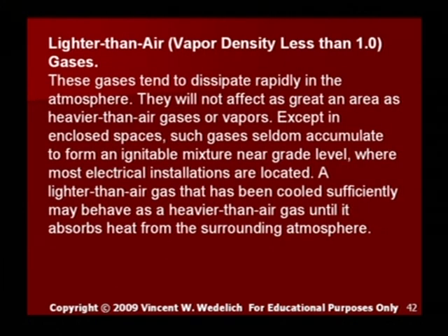Lighter than air, vapor density less than 1.0 gases. In the National Electrical Code, Article 500, you'll find a list of all the gases, and they give you the vapor density. These gases tend to dissipate rapidly in the atmosphere. They will not affect as great an area as heavier than air gases or vapors, except in enclosed spaces. Such gases seldom accumulate to form an ignitable mixture near grade level, where most electrical installations are located. A lighter than air gas that has been cooled sufficiently may behave as a heavier than air gas until it absorbs heat from the surrounding atmosphere.